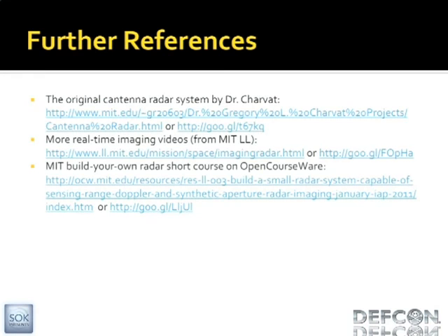Oh, well, the coffee cans are somewhat directional. He asked why coffee cans as opposed to a different type of antenna. The coffee cans are fairly directional. They were really cheap because they're coffee cans and we had them anyway. It's going to be hard to see inside this thing, so you might have to come back later and see. But the way this works is there's an SMA connector in here, and there's a little wire being fed into here. So this is basically a waveguide port. It's an adapter from that little feed antenna to this larger waveguide. And then it's basically a crappy directional antenna. But you could use something like this for Wi-Fi too, if you wanted to make your signal more directional. It's the exact same principle. And if you took some of those really big Wi-Fi antennas, you could make a highly directional system with that.